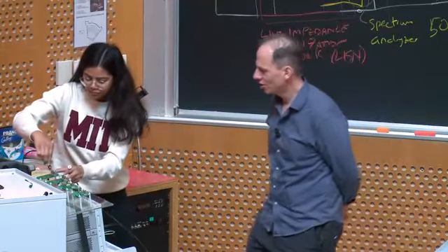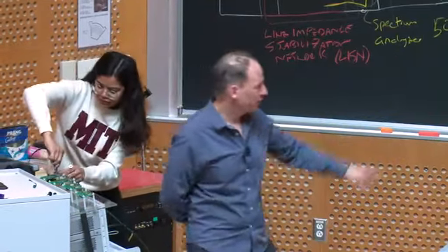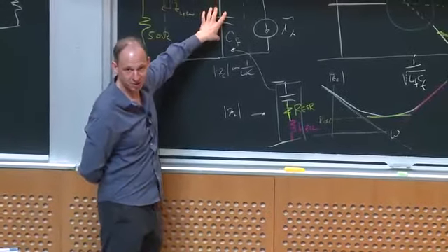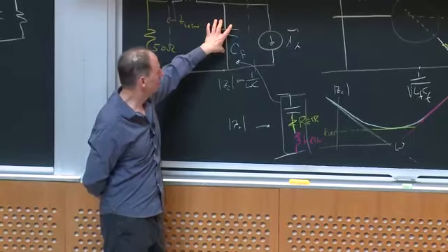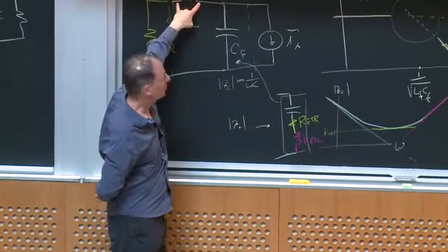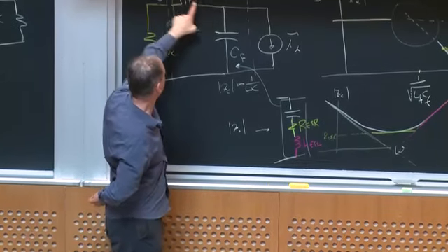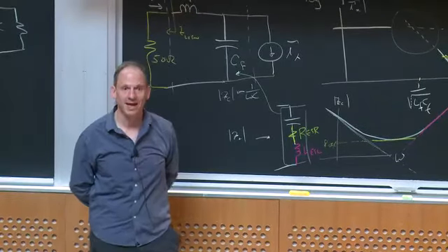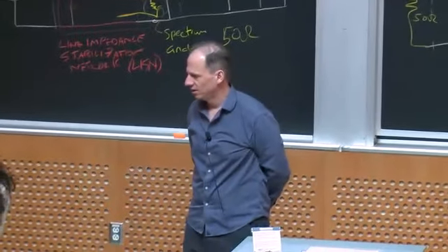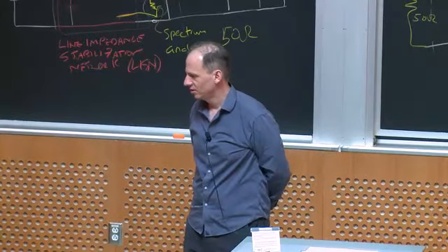The one she's going to start with is an LC filter just like this. And all that happened is we were sloppy about how we inserted the capacitor, so there's a little extra inductance in here, and the inductor, we placed traces nearby, so there's a bit of extra capacitance across it, okay? So that's the first trace we're going to see. And let's see what this does.